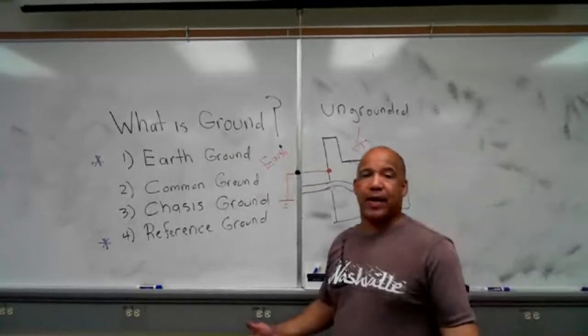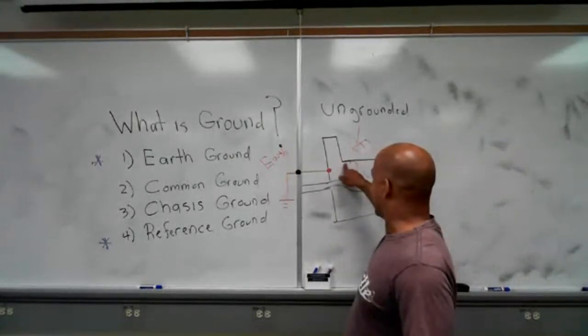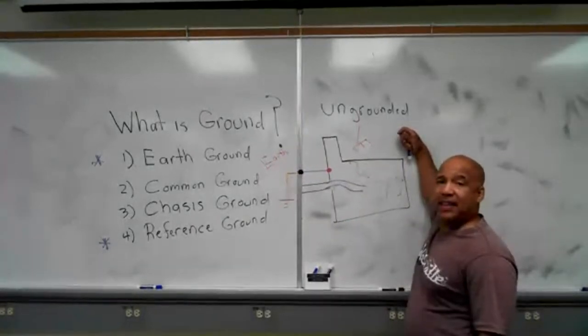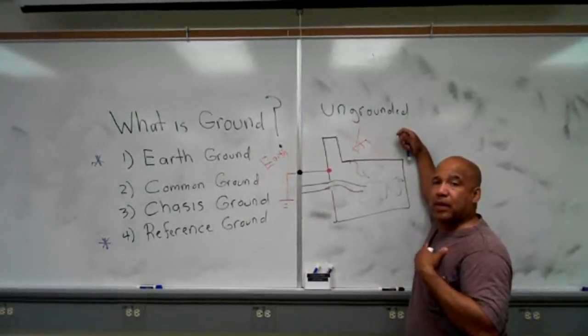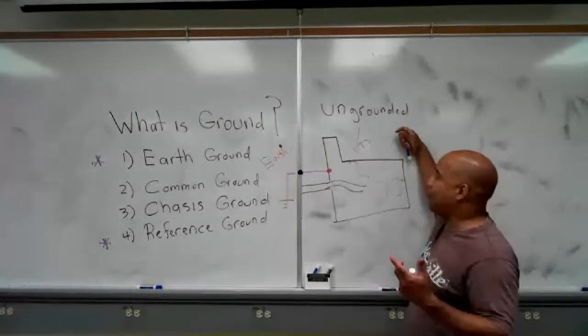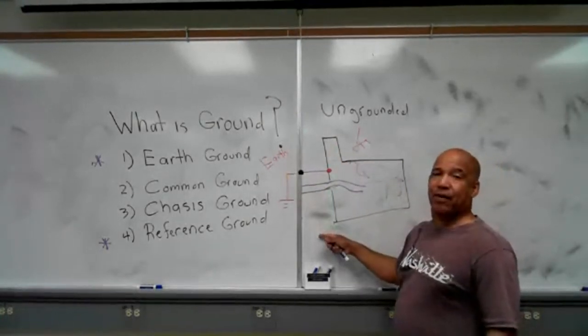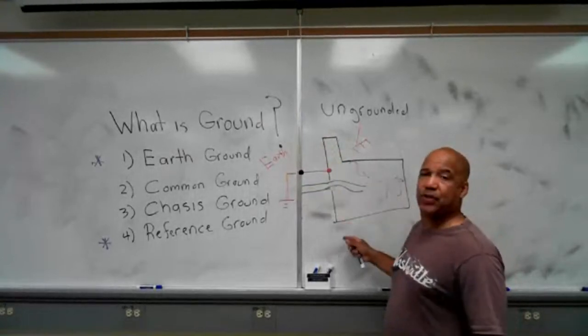So let's say I walk in there now, I have the same situation where I have a broken wire, it touches against the case, and it electrifies it, and now I come in and I lean on it. If I lean on it and I'm grounded, current will not go through me because it has no reason to go through me, because I'm at the same potential now as the machine, because it's already tied to ground. By tying it to ground, you put the case at ground potential.